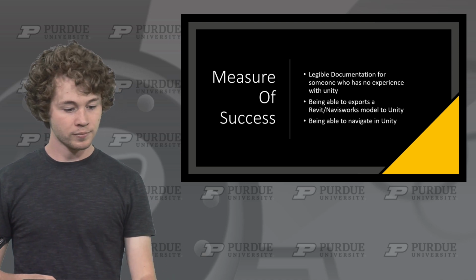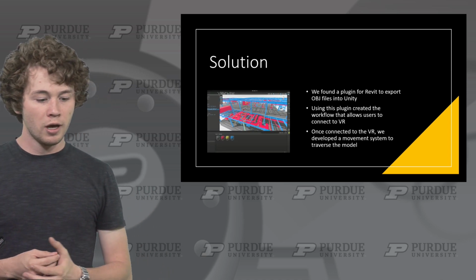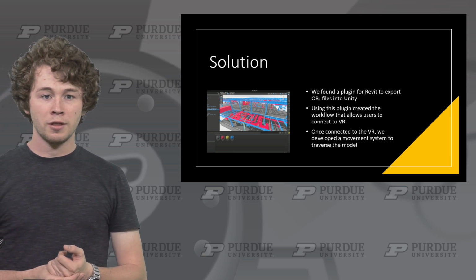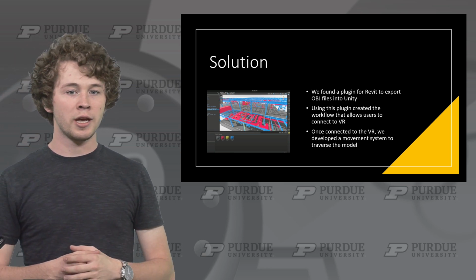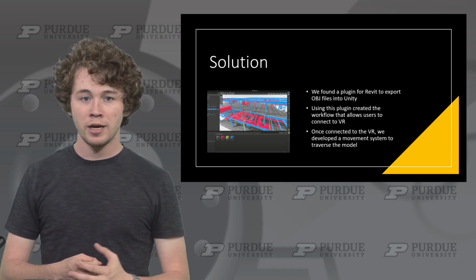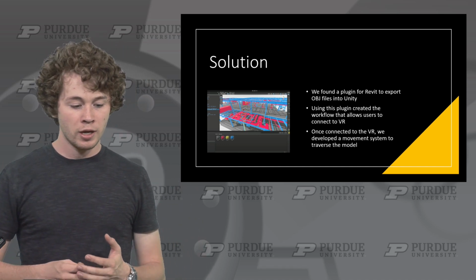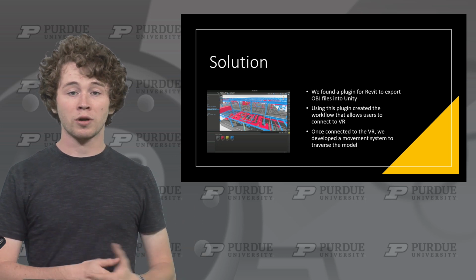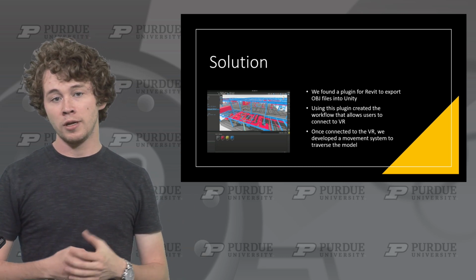So our solution, we found a plugin for Revit that allows us to export .obj and .mtl files. These are files that Unity can in fact read, and that's why we chose it as the program. This plugin allowed us to create a workflow that operated in VR.